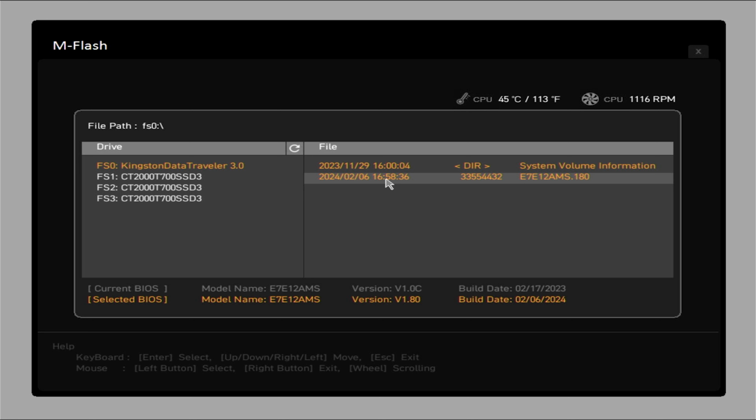So obviously by default we have the CPU temperature dictating the fan speed, but you can pick another point on the motherboard. For example, if you want to have the case temperature, the system temperature, dictating the case fan speed, which would probably make much more sense, then you can select system, and that will now adjust your fan speed based on the system temperature. So the system temperature down here, as we can see, is about 33 degrees. So you probably need to play around with it a bit yourself, but that's half the fun of this thing.